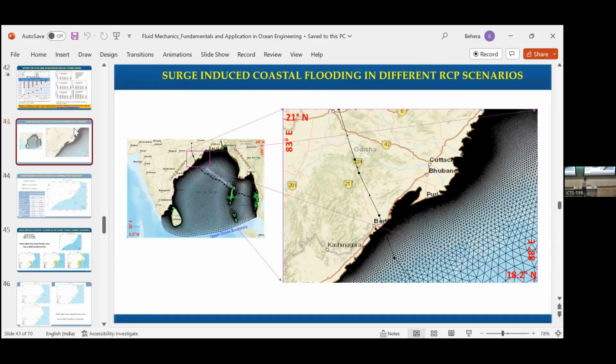Based on the zonations, we have these depths as well as the zoning. So priority is fixed. And when we actually design the structure, as I said, the structure has to be elevated to a certain height. That floor level, we call it flood level, we give it. That level also we decide based on those things.